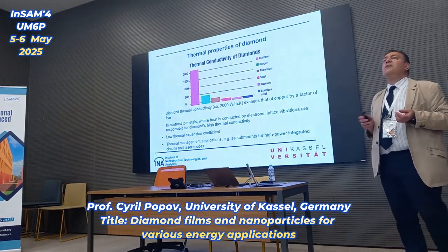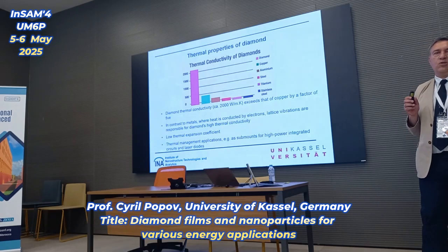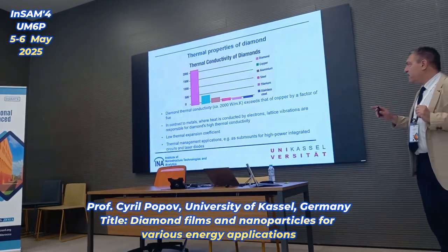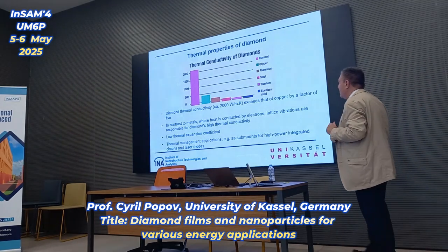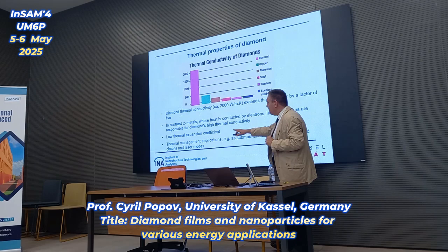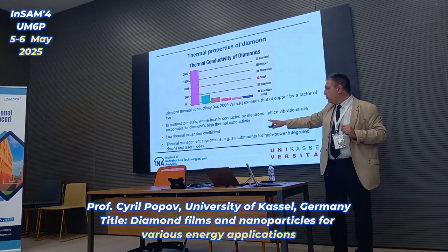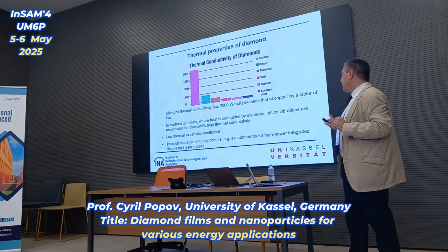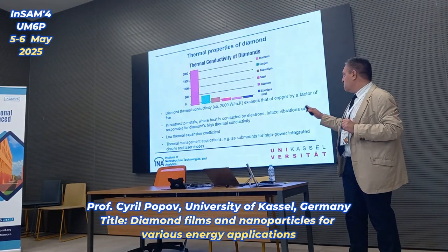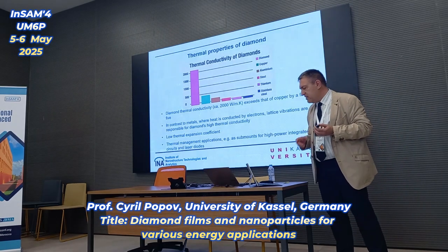And as I mentioned, diamond possesses the most dense lattice possible. That's why these phonon vibrations are so effective at conducting thermal energy. In addition, diamond has a very low thermal expansion coefficient, which makes it an excellent material for any thermal management applications, not only in this case fusion reactors, but also submounts for high power integrated circuits, laser diodes, etc.